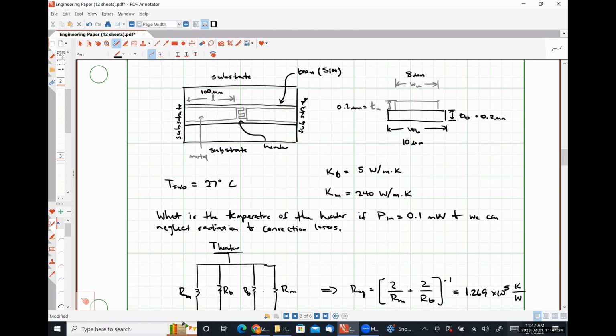So it's two materials fused together with two different coefficients of thermal expansion, and that coil expands or contracts due to temperature changes, and it will touch a contact when it expands so much, and we actually spin the coil when we turn the temperature knob to make it slightly closer to or slightly further away from that contact.